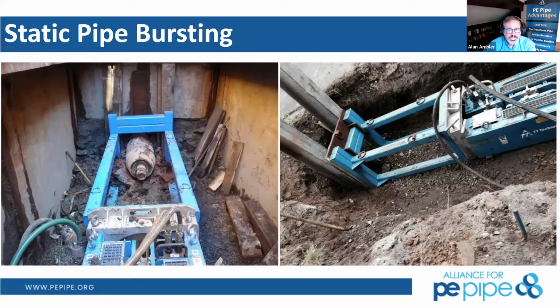The extraction cage doesn't necessarily have to be aligned for the entire pipe bursting mechanism. Sometimes they pull that machine back, install the extraction cage when they're nearing the end, and then remove the equipment. And the proper alignment of the machine, as you'll see here, is resting on I-beams that have been pushed into the ground, which stops and resists that force from moving forward through there.